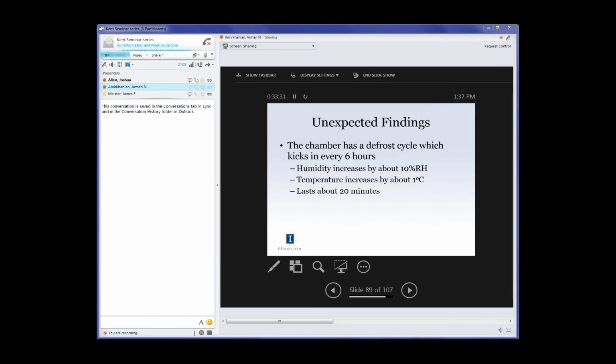So the beam was responding to just that slight change in RH and temperature change. Temperature change we didn't think had a large effect because the beam is so small, there's really no gradient that would ever develop. But just that 10% humidity, it was quite shocking that that had that much of an effect. So we decided to play around with that.